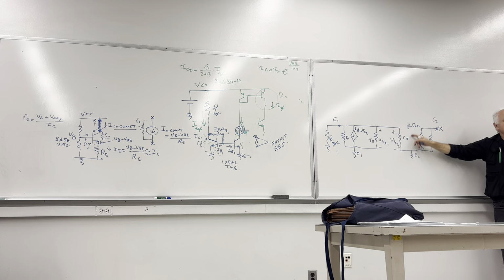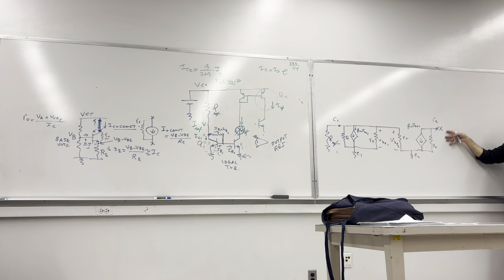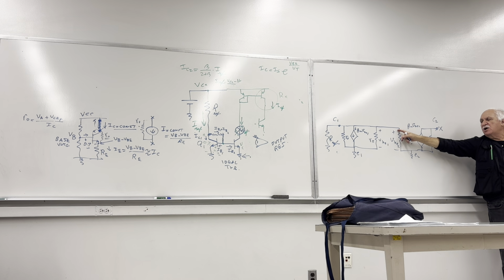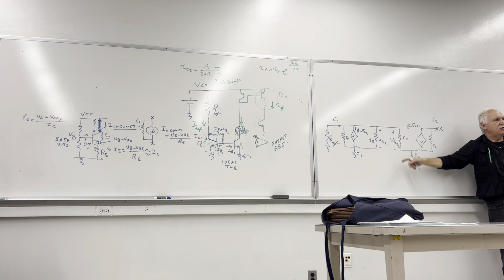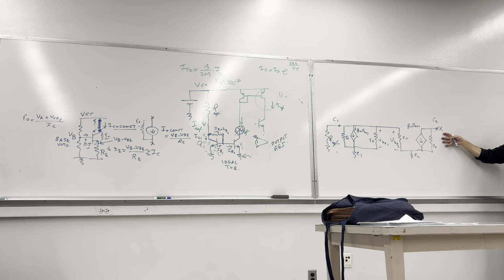So there's an opening in here. Put the test voltage here, this will not respond because it needs a voltage in here, and there's no way of creating voltage here. So with the test voltage here, we'll see this open. Therefore I test will be V test divided by RO.